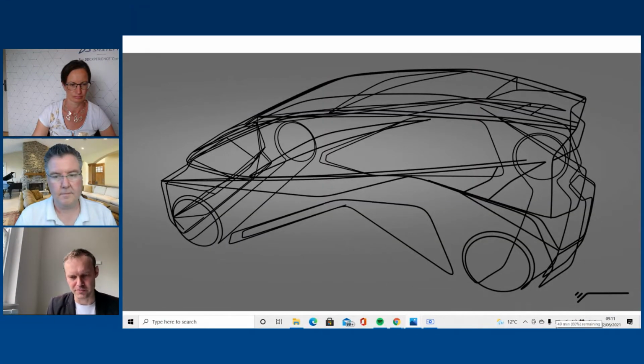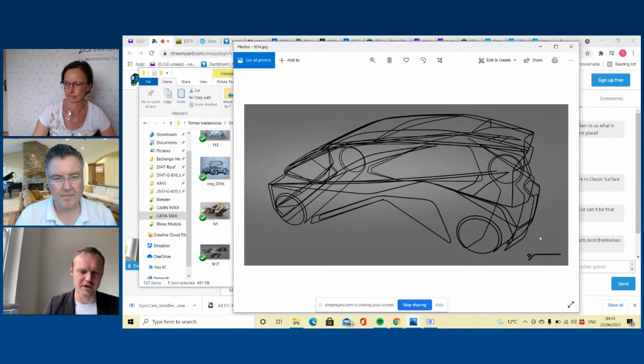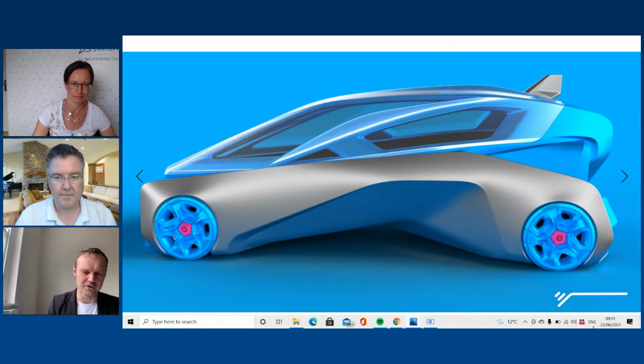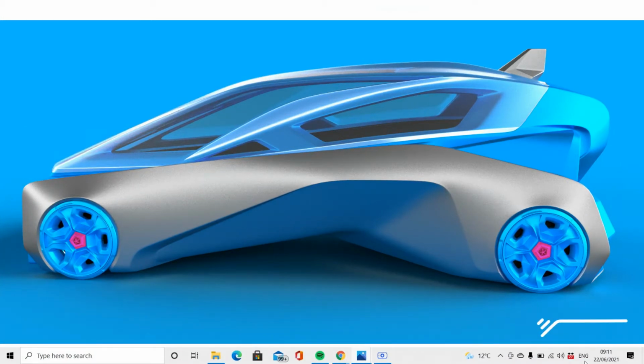Yes. So the step in between is important. So it's basically the same exterior, but you can see this is actually a 3D sketch based on the low poly proportion model. So what you do is the same thing I showed in the video just now, you 3D sketch on your proportion model, and that is a styling exercise that you do. And then finally, when you've done that, you project the surface on that 3D sketch, and that's the result of that.